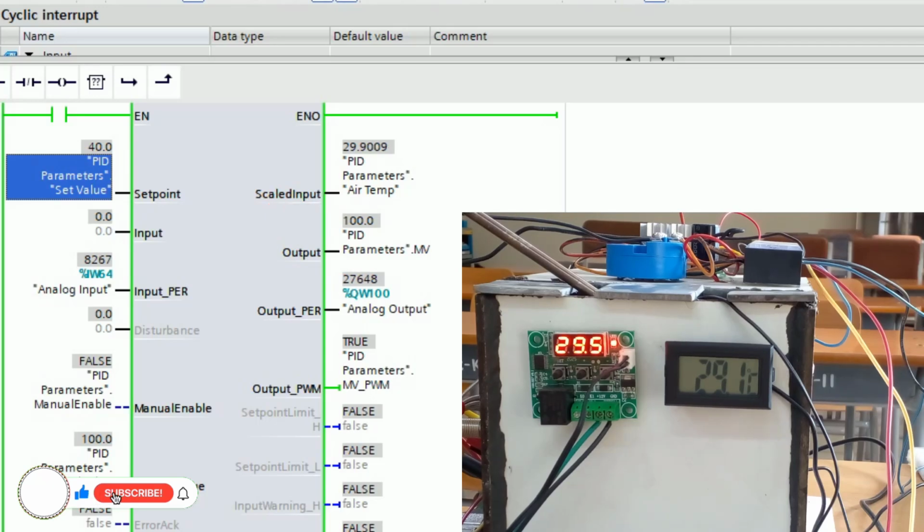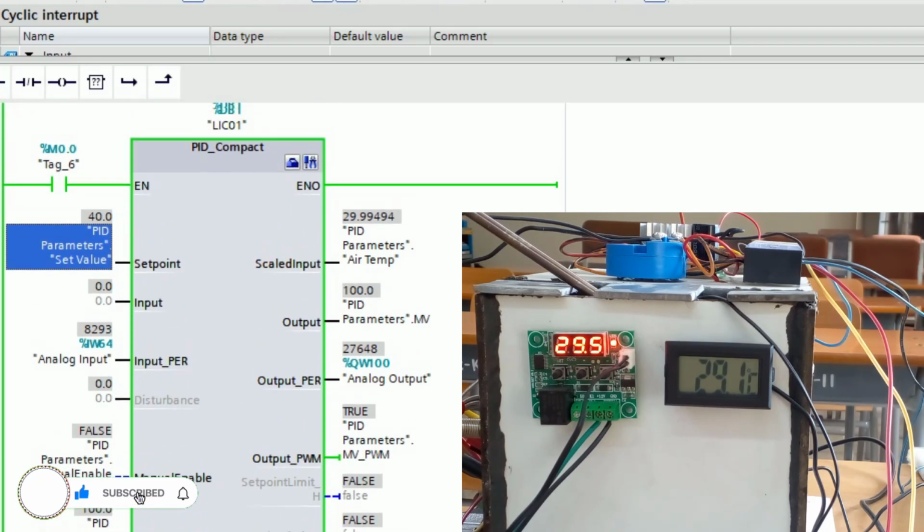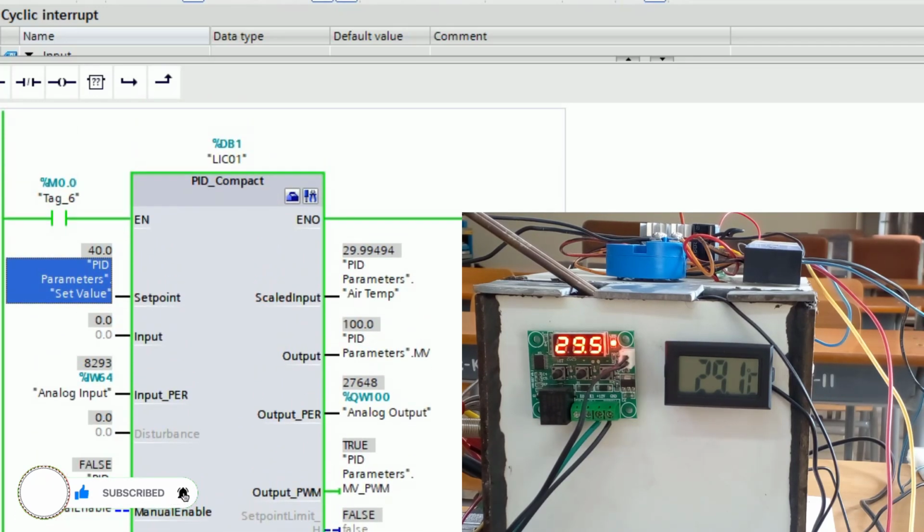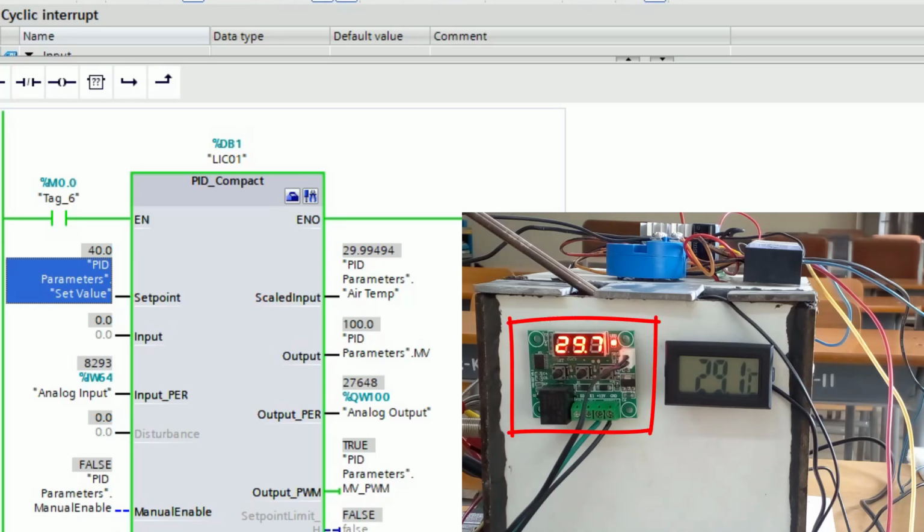The chamber outlet temperature is rising now, that is visible in the controller parameter process value. The chamber outlet temperature is also visible from the temperature meter located at the outlet path of the heating chamber. Now continue to observe whether the chamber outlet air temperature reaches the target value that has been set in the PID parameter set value.